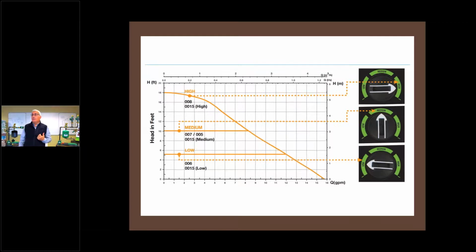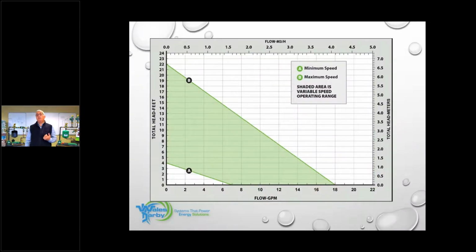Your other option is going with the VT2218. Now, could I use one of these per zone? It could get pricey. To me, I would use this for the one pump option. So still, I'm going to be at 5.2, and my plot would be right there on the pump chart. All right, and then my head loss at 6 feet of head would be right there.